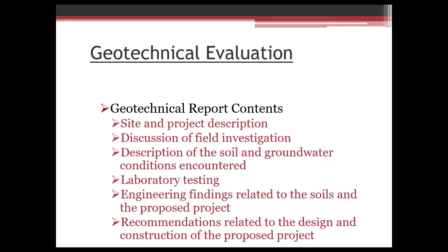A little bit on the laboratory testing that we do, and then we go into our section on the engineering findings and recommendations for design and construction of the project. And that's where you're going to find what the bearing capacity is, what the parameters are to use for retaining walls, the different soil properties that we have available, different materials that we recommend for backfill or for slab subbase. And that type of information is in that last section.